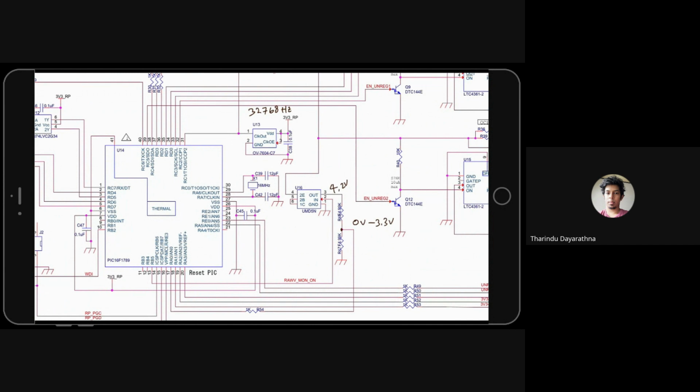Did you understand? Basically, we isolated the raw voltage from the reset PIC. If we need it only, we enable and measure. Please remember why we use this divider: because the PIC cannot measure more than 3.3.